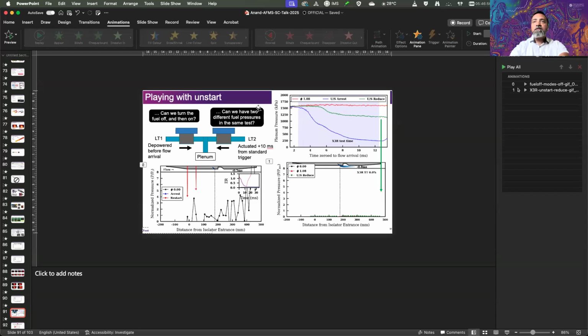So that's an ongoing debate. My American colleagues, when I show them this, they call it the ram mode. And what they believe is it's not supersonic combustion anymore. It's basically you have a pocket that's subsonic where it's burning, or at some point it has closed completely inside and it has become a subsonic combustion mode inside. In all our simulations, we have shown that we do have a persistent supersonic core. So, we beg to differ. We call that dual mode. We believe ram mode occurs in scramjets.